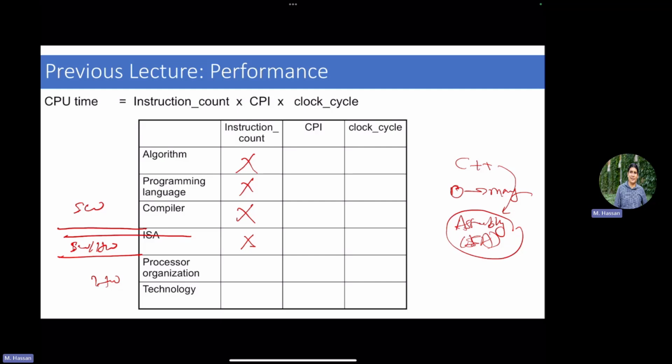That's also a good point. So one example for this is if you have a processor that would have floating point instructions versus non-floating point instructions, then you say, well, if you have floating point support, I mean, able to execute floating point in hardware, you enable the compiler to create floating point instructions that are executed in hardware, and then you only create that instruction.